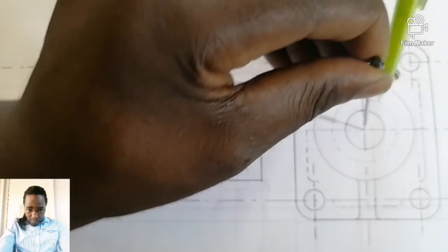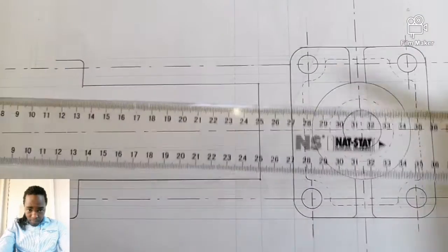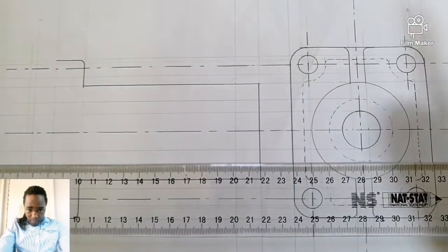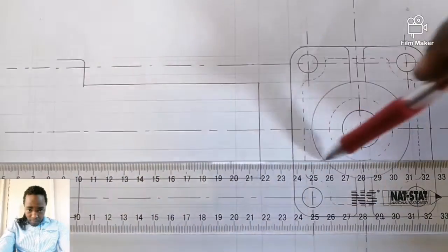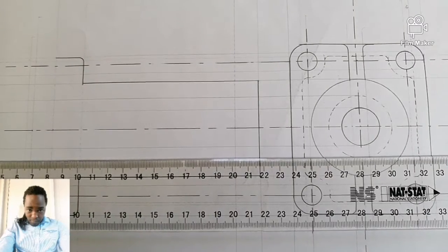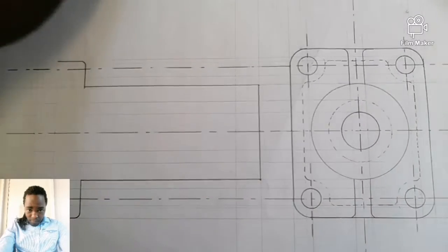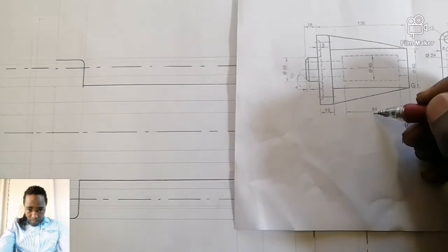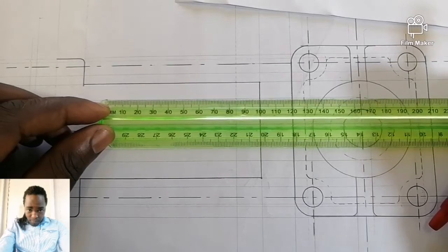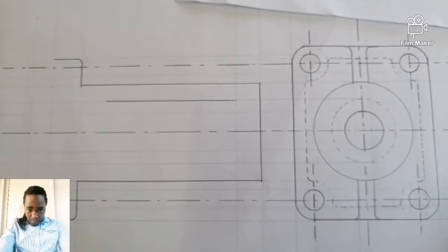So you can see that we are drawing these views more or less simultaneously. So now you can project them towards your left hand side so that they give you a clear picture or understanding on your front view. So from here till here is 84. Simple, huh? So now from here I can measure the 84. There is 85, 84 is here. Or else I can even draw it dark.